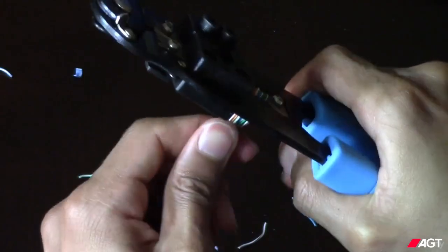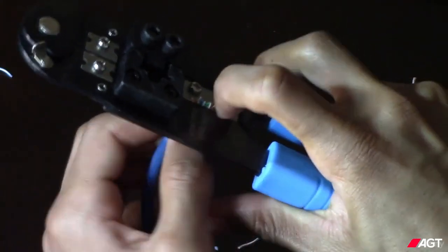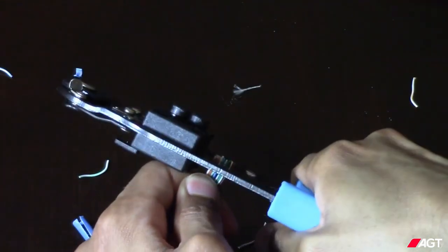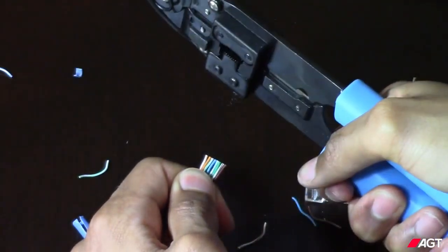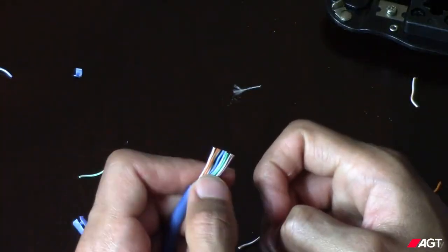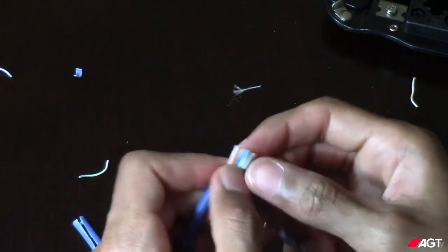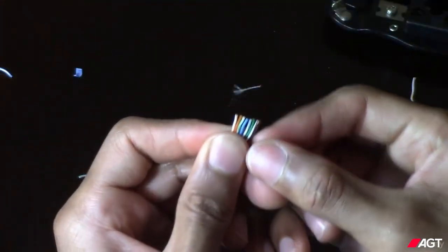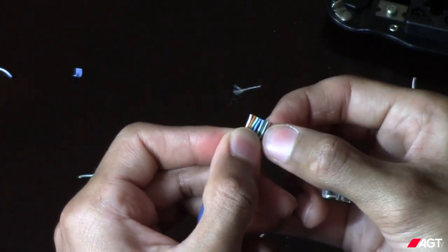Holding your wires in place with the crimper, wiggle them around a little bit and straighten them out. Make sure the tips are close together too. Then make the cut. Sometimes the wire can look uneven if they bend a little, like my blue wire, but that's okay. They'll straighten out once the connector's on. So that's pretty much all there is to color coding. Now that the wires are even and ready, we'll install the connector.